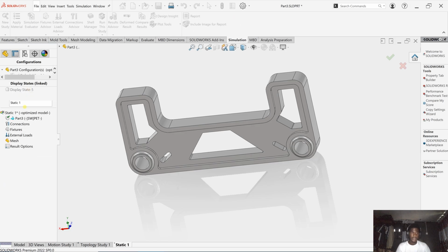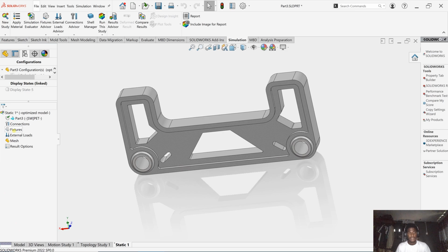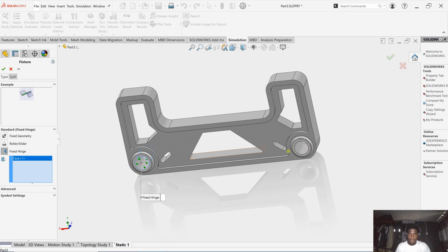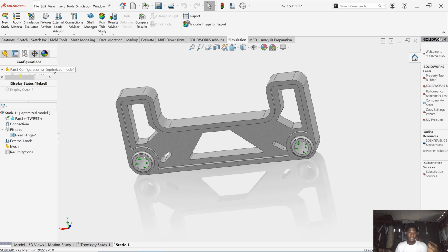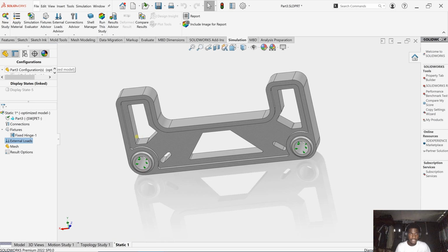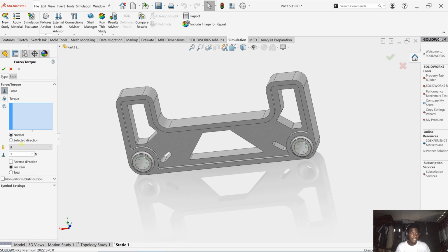The last study we did on the part that wasn't optimized, we got about 1 millimeter of displacement. Let's do the same study on this part. We fix this, and we're going to use the same parameters so we can compare. That was why it was important to write that out. I've already showed you how to run a static simulation using the same data I used in the other one.